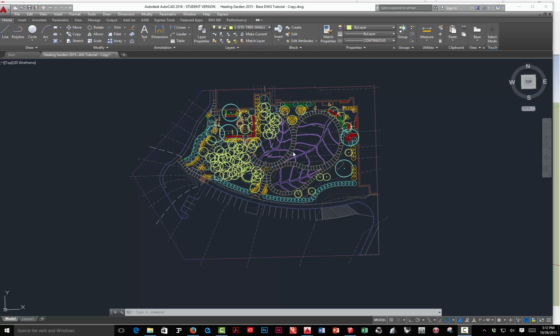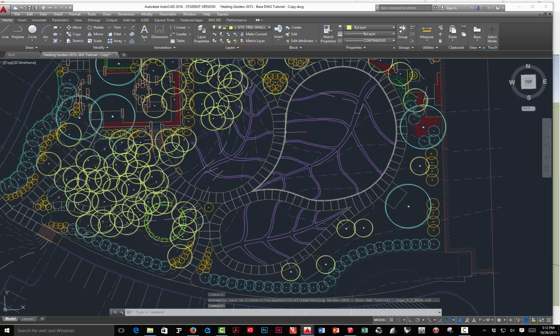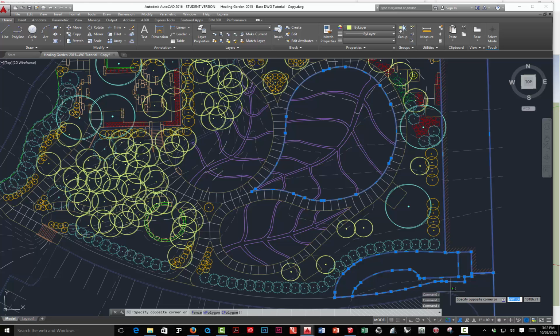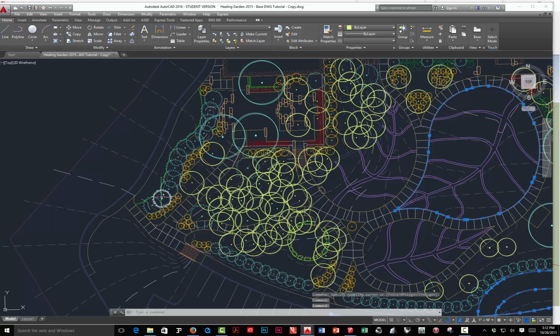The first one is flattening geometry in your AutoCAD file to make sure there's no elevations in them, except of course for the contours. And the second is exploding the polygons that have arcs in them so that we end up with arcs in SketchUp instead of little line segments. So to do that, the first thing I'm going to do is layer isolate all the flat work, the hardscape, the things that sit on the ground plane, paving edges, that kind of thing.